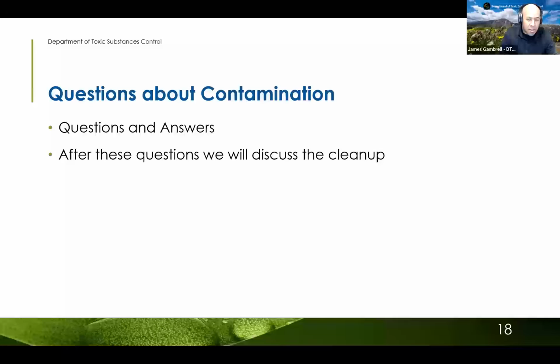So basically what you're saying, Mokes, then is that the drinking water is completely separate from the water that's in the ground, just kind of hanging out below the surface. Yes, there are two folds. First, the water that's being provided to the community is not from the site; it comes from someplace else. So that's a different source. Second, the piping that's conducting the water to each residence is above the water table. So it's unlikely that the contamination that is in the soil is getting into the piping and impacting the water quality.